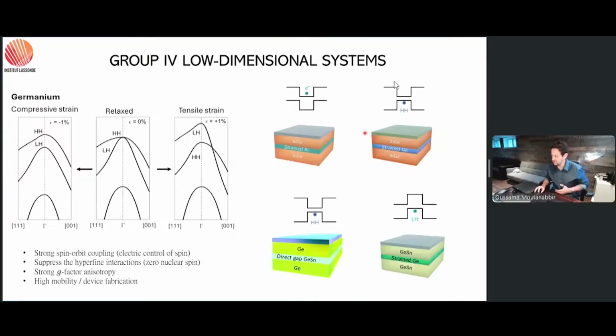So this is exactly the top, the two heterostructures I mentioned. You can either work with an electron spin. This is silicon germanium, and I'm sure that people, Sadhu has been working on this, I think. The challenge on this heterostructure is that you're working with electrons in the conduction band of silicon. Conduction band of silicon is messy, and it comes with a lot of problems, valley splitting being one of them. And you're working on a system that is highly strained. There are dislocations, so there may be variabilities coming from modulation of strain at the surface, alloy disorder at the interface as well. And the heavy hole.